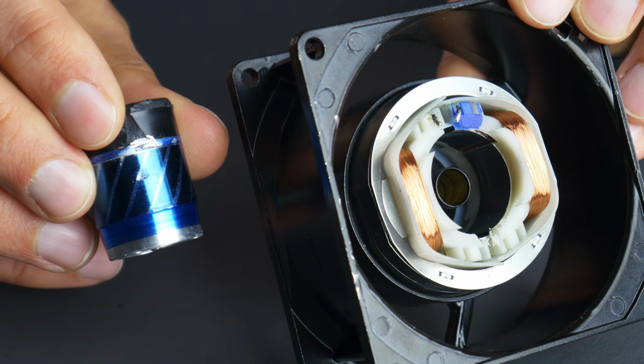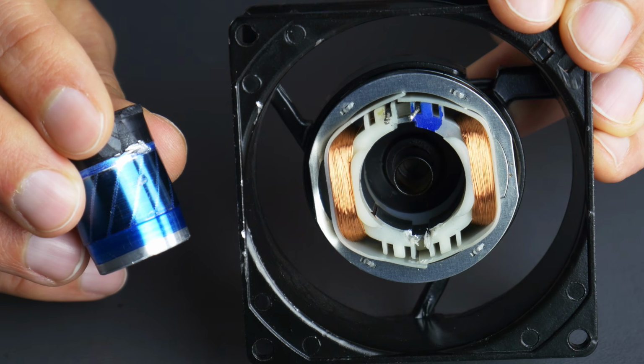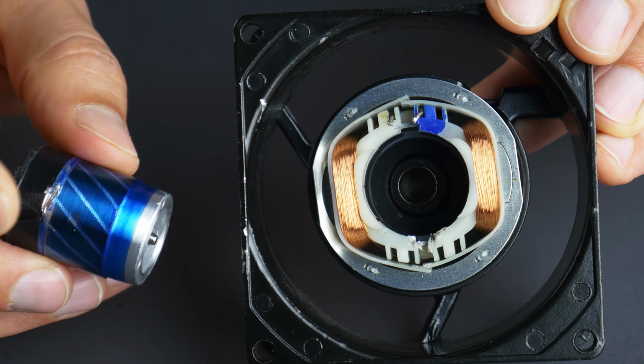AC motors are interesting because with DC motors, the big challenge is getting the current to switch direction. Not a problem with AC motors. With the alternating current, the current changes direction cyclically, and the motor is usually what we call an induction motor. No wires or direct connections are needed to get current into the rotor. It just happens through the changing magnetic field, making it very durable.